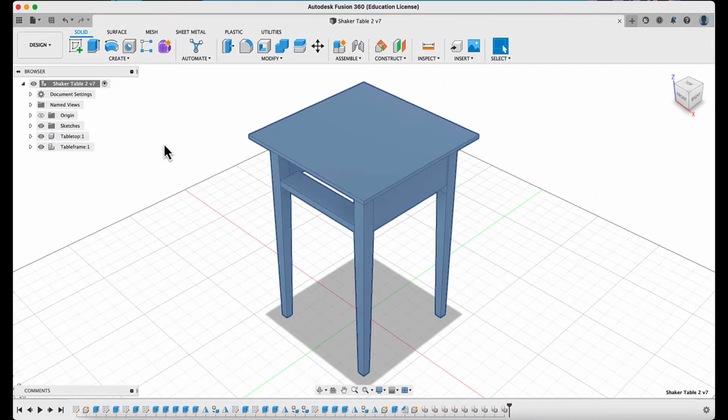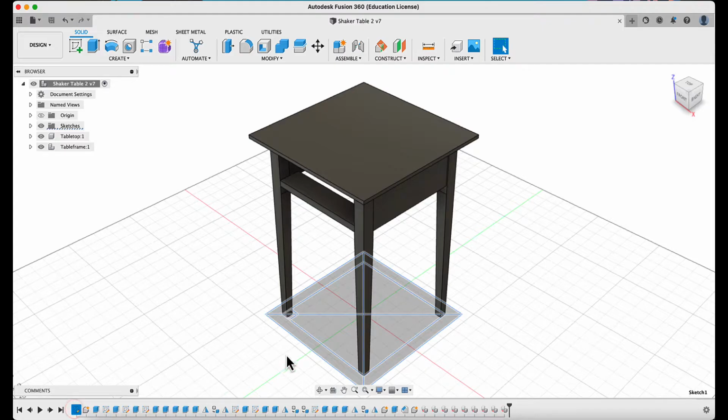In any case, that's something that you can just have a bit of a look at. Where that becomes useful is if you've gone and saved something and you want to go back to an earlier version. Another thing that you've probably seen build up is this down here, which is the timeline. This is a way of being able to go forwards and backwards through your project. In this case, this takes us all the way back to the very first sketch, and then these are all of the actions that we've done up to this stage so far.